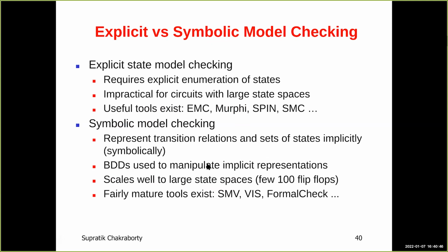And we will see that some of the operations that we have seen earlier can be used to basically do this search, this backward search on this implicitly represented state transition graph. We don't want to represent it explicitly. We want to just use the circuit, the finite state machine circuit, to represent the state transition graph.